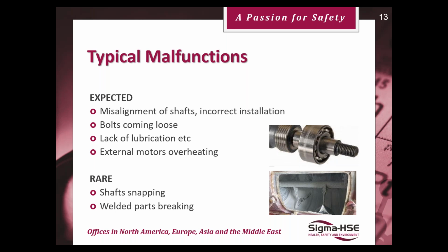Again, this is all outlined in the standard, the guidance. This is probably the tricky part of this assessment. Understand what scenarios to consider. Is it credible? Because when you fill in your table, you have to give a reason why you've considered it. So, for example, you might have an expected malfunction, say trapped metal ingressing into your dust handling system, and then you have to give a reason, and then you have to justify what your safeguards are.